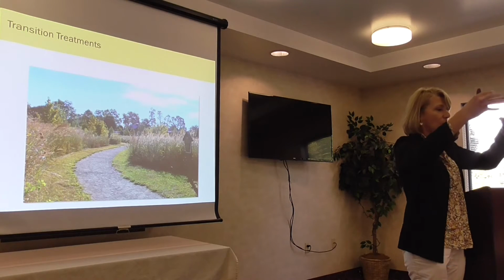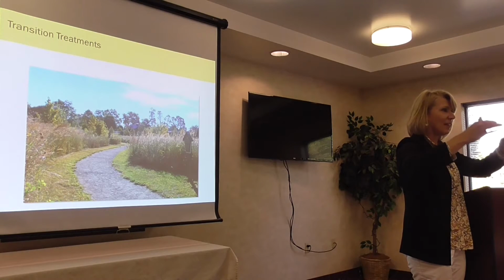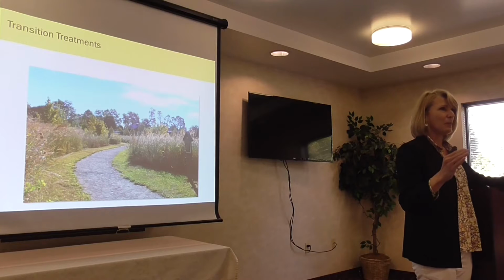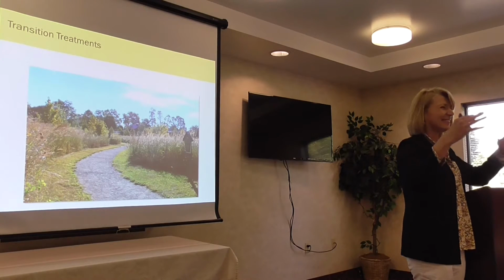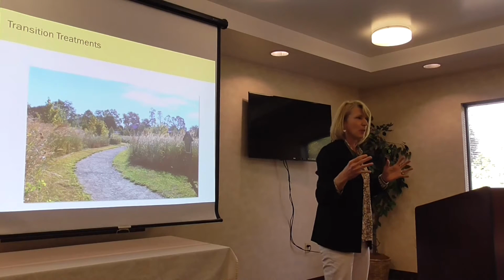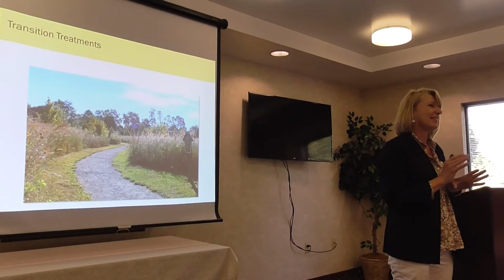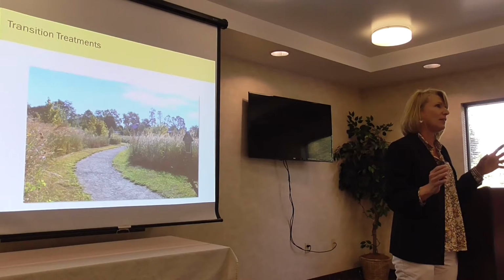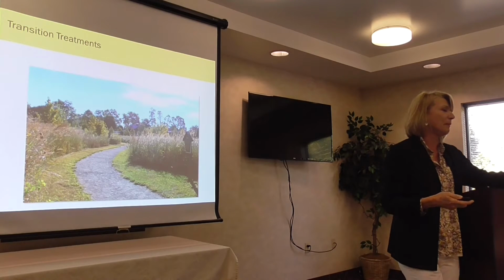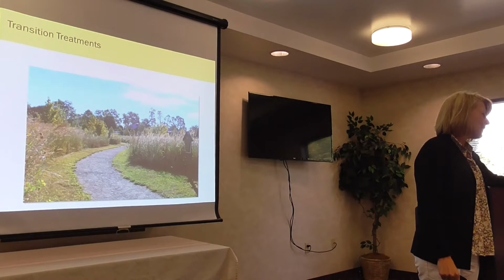which is typically easier than if you have a bioretention area and then you have a berm the whole way around it, and then you have a meadow on the other side. Well, you end up, sometimes they'll start mowing that berm in between, and you get these just kind of strange areas in between. So just don't not address it. The best thing is just come up with something so that you at least don't end up with these kind of strange intermediate areas.